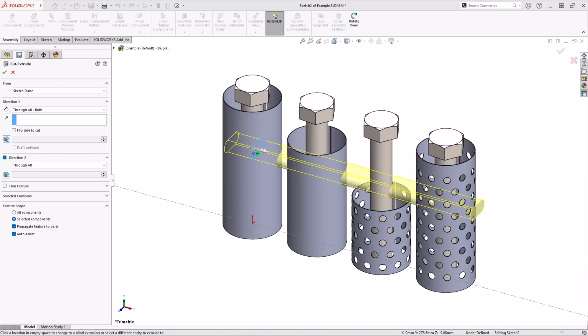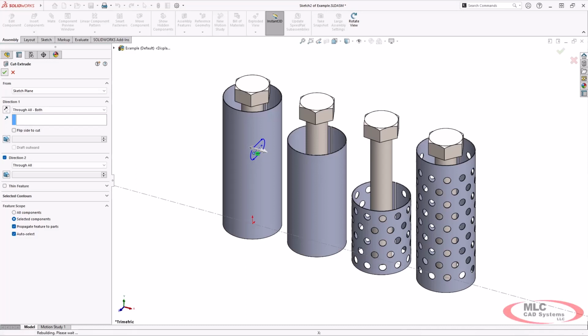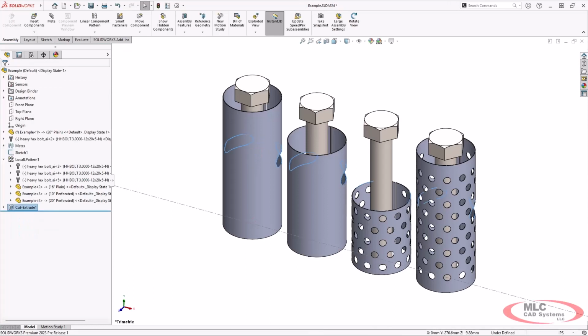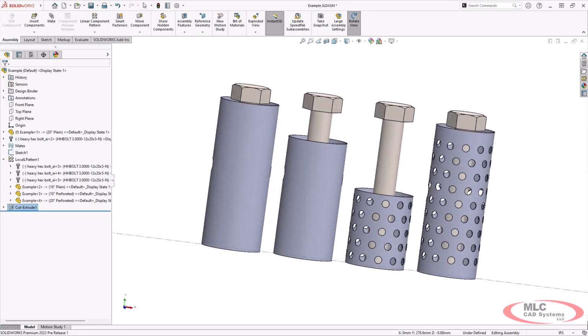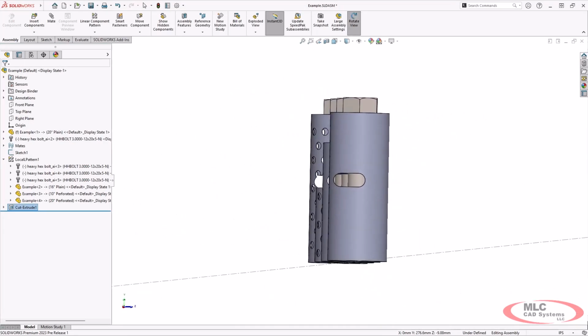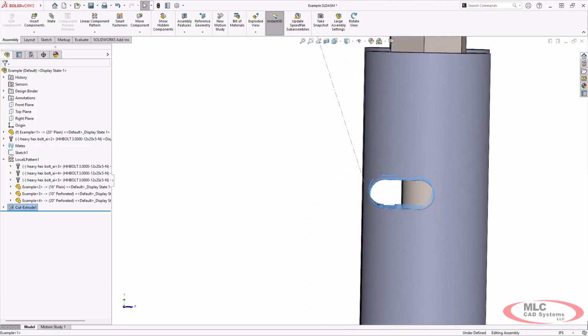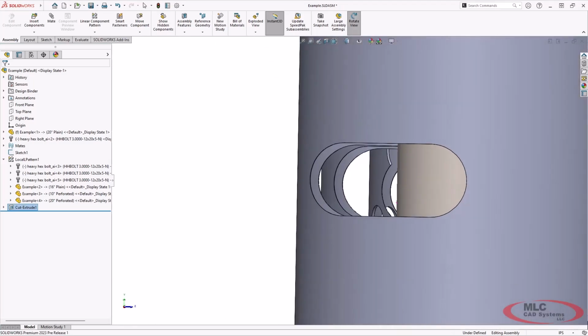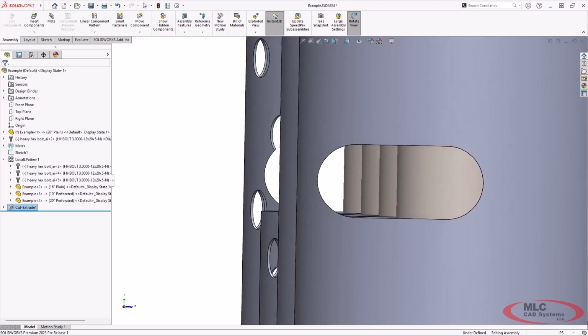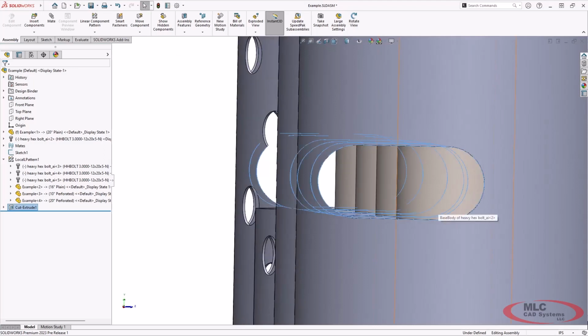So what I'm going to do next is click OK, and I'm going to let SOLIDWORKS calculate that feature and go ahead and create that. And you're going to see something very special. It's super easy for me to exclude toolbox components because I literally don't have to do anything in SOLIDWORKS 2023. SOLIDWORKS, by default, is going to ignore toolbox components when I'm creating an assembly level cut. And let me show you what I mean by that.